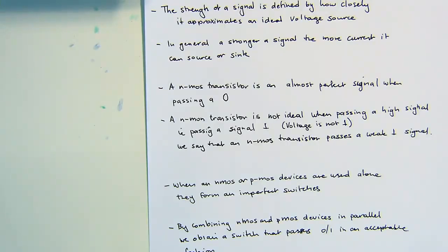So in order to have the best gate you can produce, closer to the supply rail or to ground, the way you would configure it is PMOS, NMOS. So don't ever produce an inverter using NMOS and then PMOS. It's not what you would do.